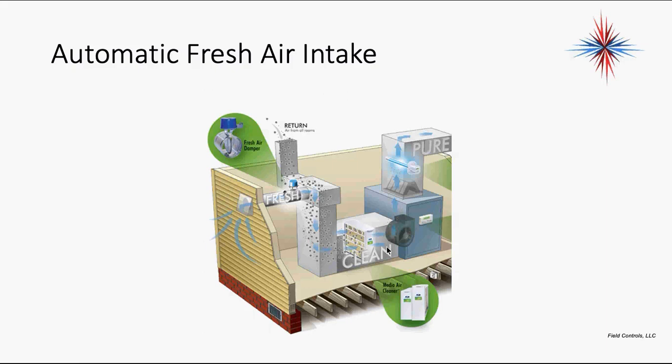Even without running, you're going to have a little bit of leakage going out of the building. I'd rather have that than a little bit of leakage coming into the building, because again, I'm controlling it. If I can control the airflow coming into the building, filtering it, cleaning it, and cooling it, I'm going to be in much better shape than if I don't control that airflow going into the building. So this diagram actually says a lot.